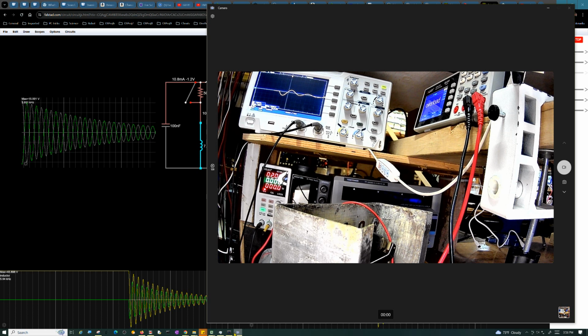So the bigger it gets... now this still isn't storing a lot of energy. Again, I had it south of 200 milliamps, right? So it's 0.2 squared, divided by 2, and then multiply by our 0.0072 Henry core. It's about 144 microjoules according to this. So not a lot of energy at all. But still, if you were to carry this up into the ampere range and really start to put some energy in that.